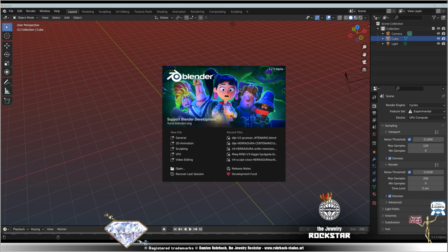So I am using the bevel modifier to keep the edges sharp, because in this design that they sent me, the edges are sharp. Let's see, if you remove the bevel here, you get a more organic finish with rounder edges and shapes because of the subdivision. But in this occasion, we want this. The edges are flatter and then rounded on the edges thanks to the bevel. And we can also have a look at the segments of the beveling. You can try 2, 3. Okay, I think 2 is great.